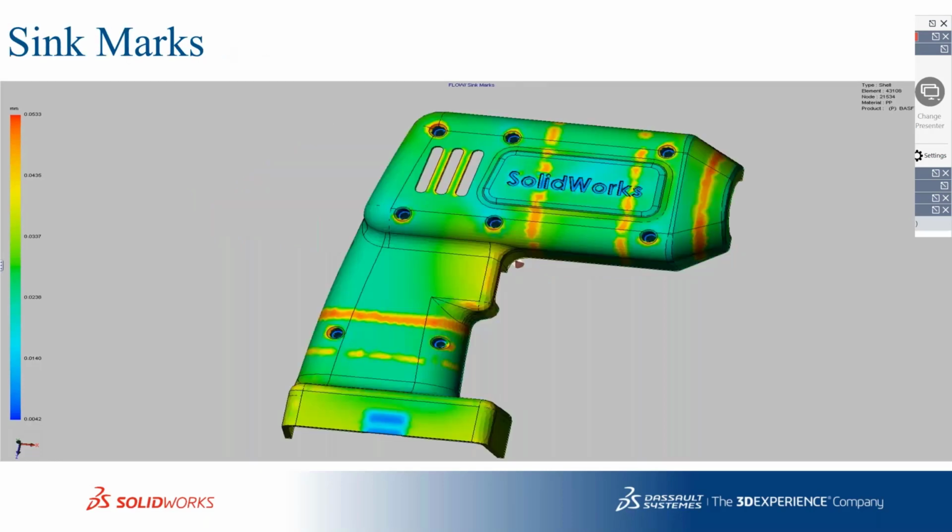And the sink marks, you can see the sink marks, where on the other side there are thick inserts which give me the sink marks, and how to avoid that, whether to decrease the size of the inserts on the bottom side, or how we are going to do that. As a mold designer, I will have different iterations to avoid these sink marks.